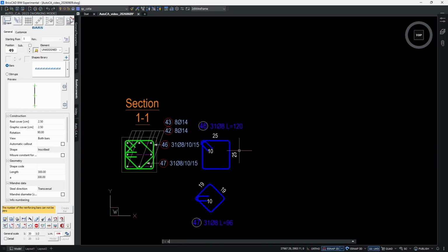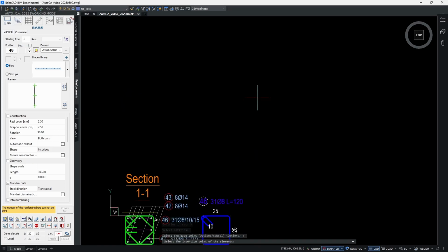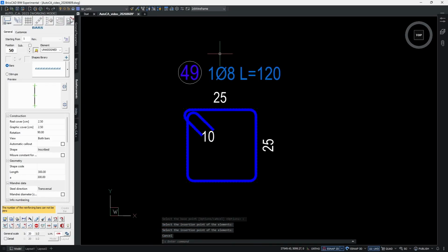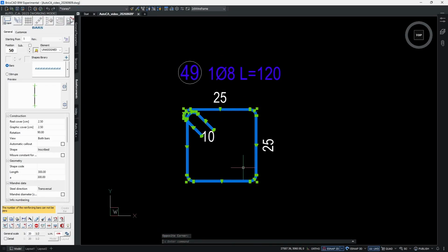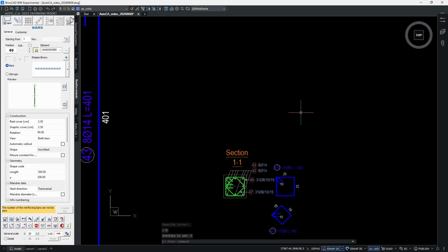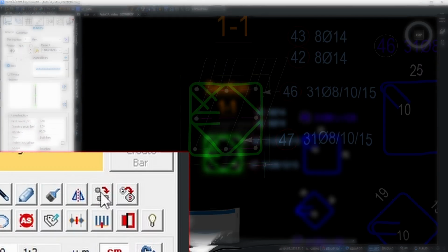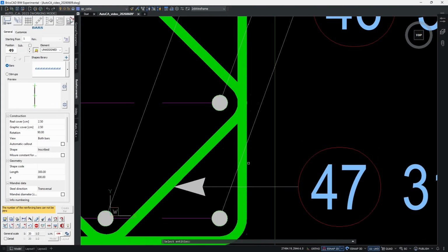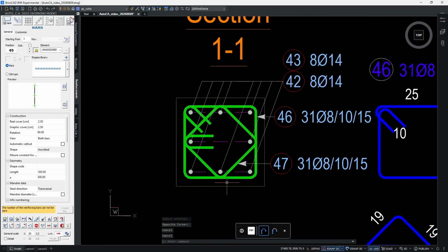If I copy an outside stirrup though, then this is gonna count only 1, as you can see here. So that's it. If you only copy the internal bars, the copy element, this is proprietary for AutoCAD. So it shouldn't be confused with the simple AutoCAD copy. So whenever you want to make multiple entities of the AutoCAD type, you need to use this one, okay?